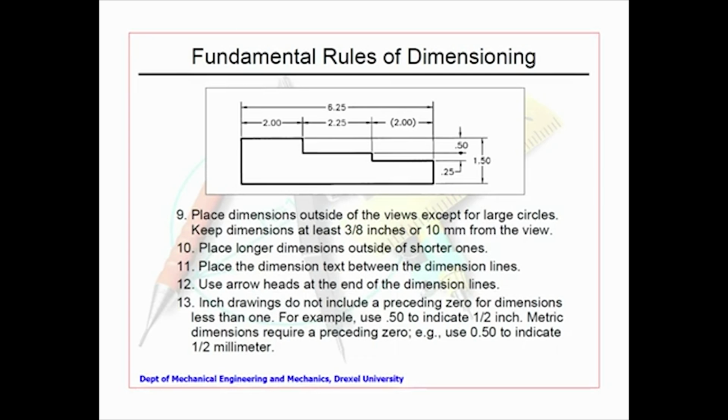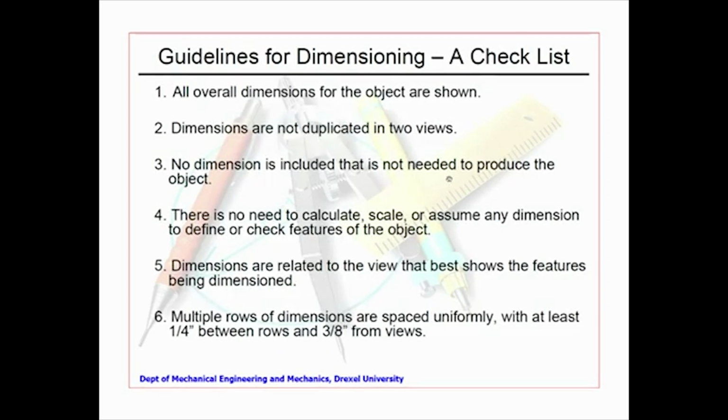confusion. Now, if you look at the right side, I have 1.5, then you see there is a small dot here. The dot represents from here to here. Now, are we violating it? Strictly not, but it is unavoidable here. You must show this. You can't leave this, otherwise it does not make sense. If you see here, this last portion from here to here is not mentioned. 1.5 is mentioned, total 3 is mentioned. So, by default it will become 1 millimeter.